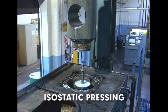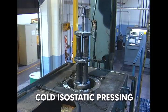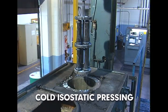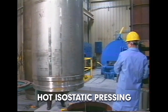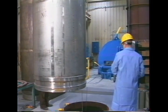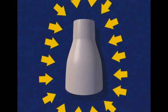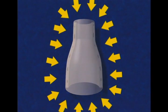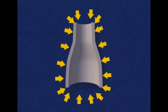Powder consolidation by isostatic pressing at room temperature is called cold isostatic pressing, or CIP. When performed at an elevated temperature, it is known as hot isostatic pressing, or HIP. Cold and hot isostatic pressing applies high pressure to the powder uniformly in all directions, thus producing consistent density.